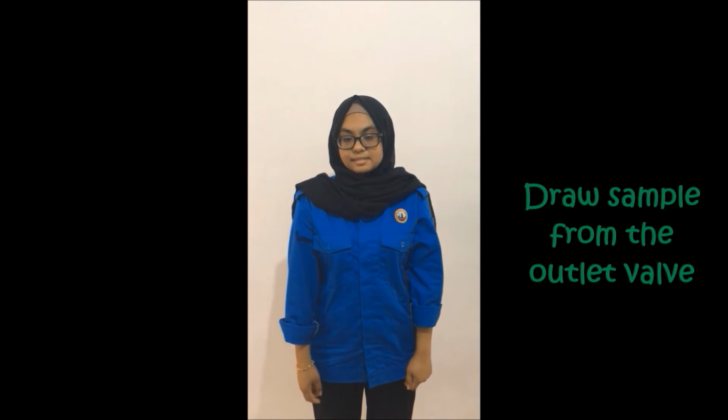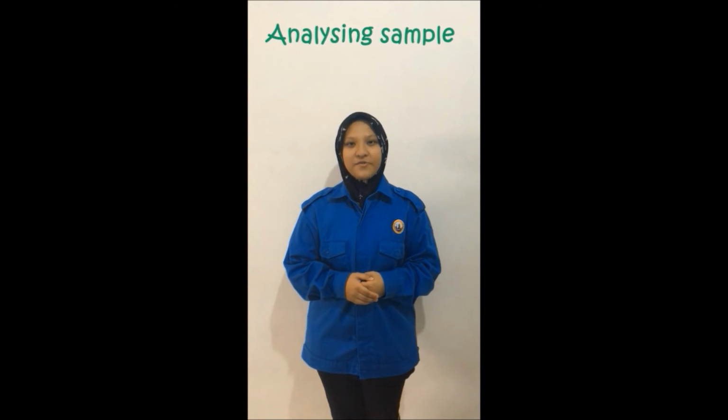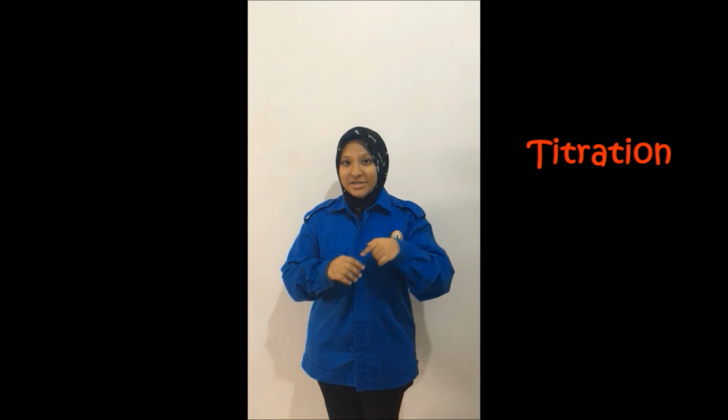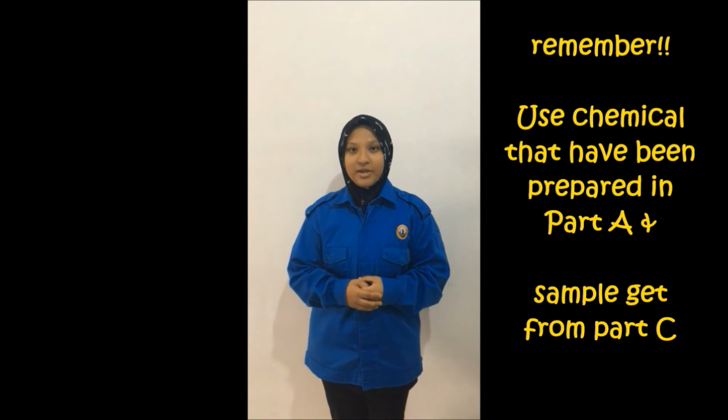Draw 20 ml sample from the outlet valve every 5 minutes. Repeat the experiment for 60 liters per minute air flow rate. Now we have arrived at the last part of the experiment, which is analyzing the sample. We analyze our sample by using the direct titration method in order to get the amount of unreacted sodium hydroxide in our sample. We use the chemicals that we have prepared in part A and also part C, and then we mix them so it will become a solution.